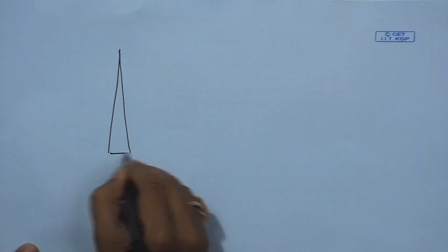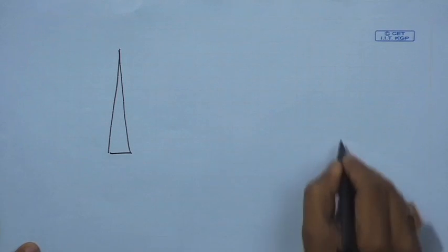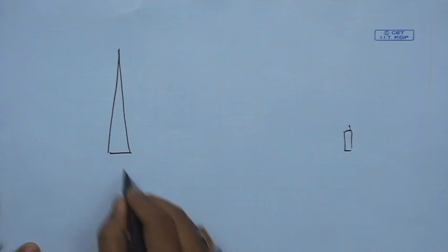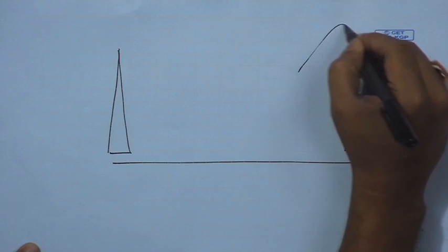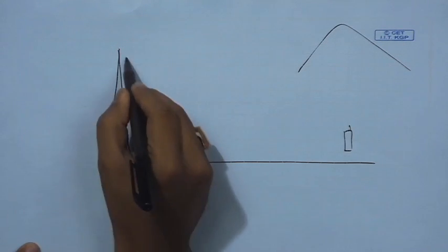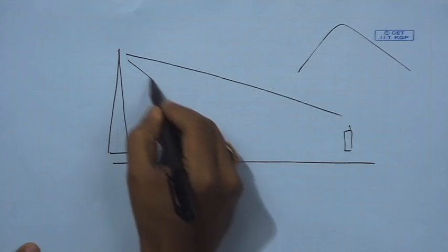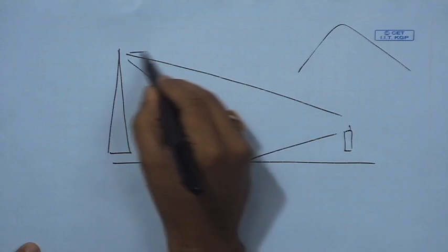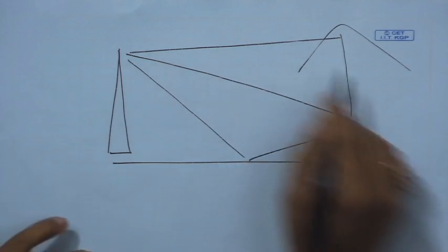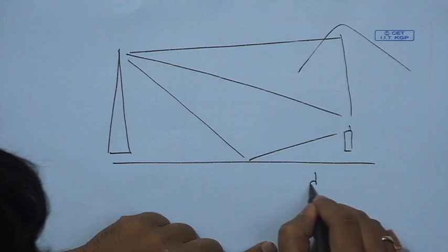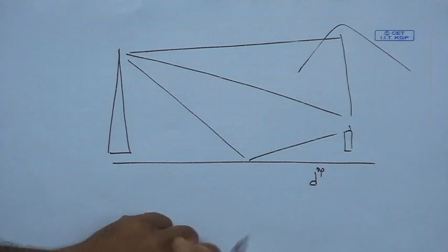we will again draw the transmitter and we will draw the receiver. So, first let us take a scenario where there is probably one hill, that means a hilly region. So, there would be one line of sight, possibly one reflected path from the ground and one from the hillock. So, this particular scenario will create a particular exponent of NP.